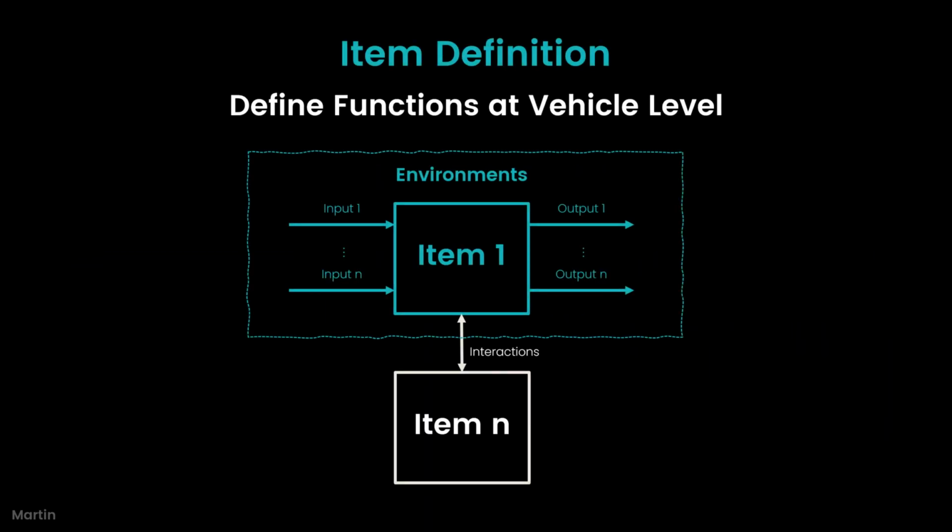An item definition is essentially the foundation document for functional safety activities. It's the first formal step in the safety lifecycle from Part 3 of ISO 26262 and defines what exactly you're developing from a functional safety perspective. Think of it as the system passport. It describes the item's boundaries, purpose, environment, and operating conditions, so everyone knows exactly which system is being assessed for safety.